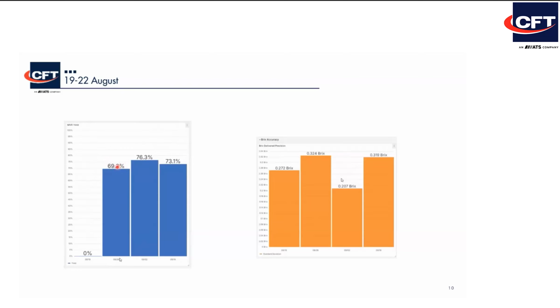Here you have to consider that 69%, what does it mean? It means that out of 100 kilowatts that you buy from the electrical network, only 69 of those are transferred to the vapor in forms of compression and enthalpy rise, and the rest are lost. 31 kilowatts out of 100 are lost into friction and inefficiencies. On the contrary, after the modification, up to 76%, 76 kilowatts out of 100, were transformed into compression.